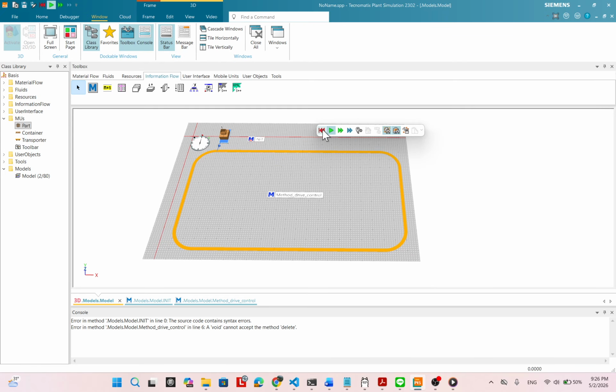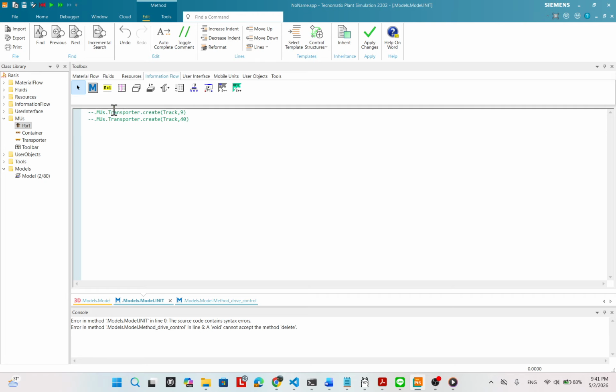Turn back. And why does the error pop up like that? I saw the problem: I commented out the two lines of the method, so I did not allow the method to create the part on the AGV at the position, and that causes the error, because there was never a part for deleting.